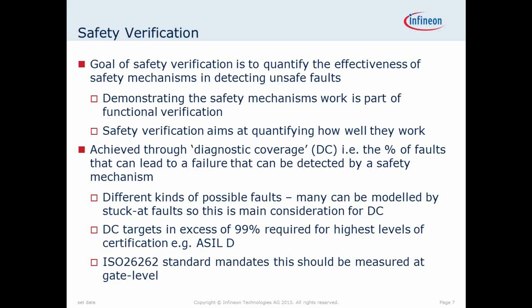can lead to a failure that can be detected by a safety mechanism. There are lots of different kinds of possible faults. There's stuck-at faults, there's transient faults, there's bridging faults, there's more. A lot of this can be modeled by stuck-at faults, so I'll focus on stuck-at faults.